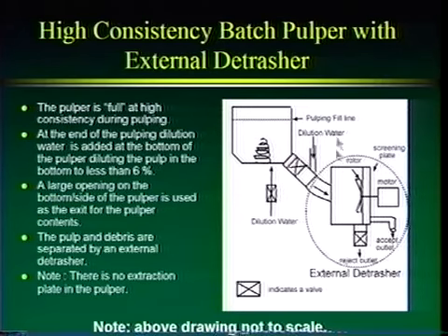So the rotor actually agitates all the material. The pulp comes in at 5% consistency, it goes through these openings in the screening plate, and it goes out the accept outlet. The large debris, things like sneakers and plastic bags and mannequins and CDs, won't be able to fit through these holes. They'll fall down to the bottom of the detrasher.